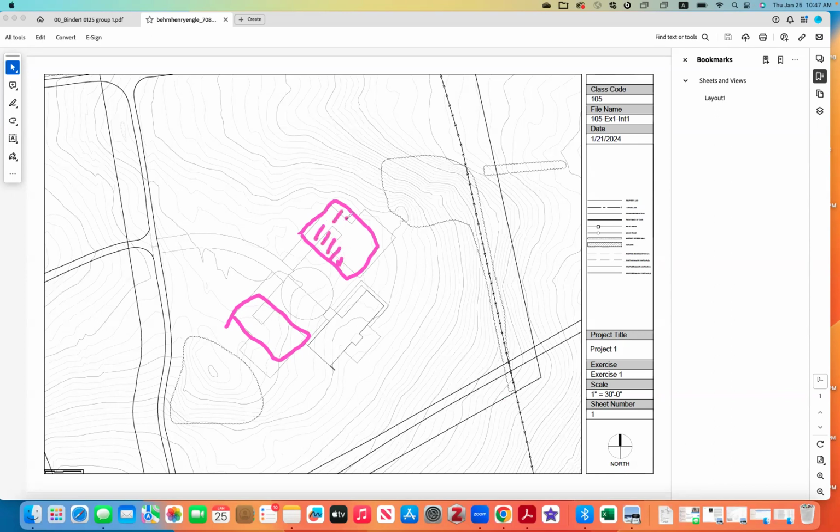In this case, you will have basically two rows of parking and your driving aisle in between. You need to keep 50 feet away from the vegetation for now, okay? You can get up to this line, that's this contour line. Otherwise, we're getting into areas that are too steep.